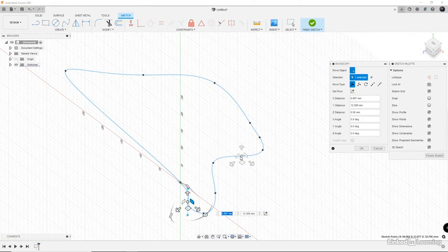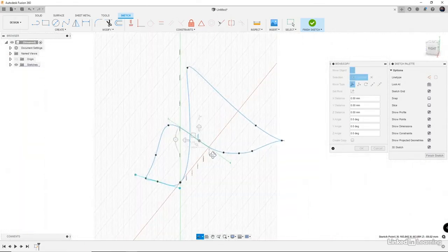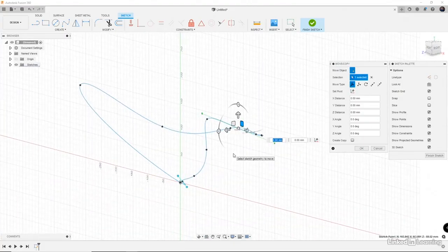The only problem with editing is it's not going to reference the construction plane that it was built on. It's going to reference the original construction that you did. So if you notice, this is referencing the construction plane that I built originally here, and this is allowing me to move this in 3D, but it's not going to re-snap to that temporary construction plane that I built for that point. So something to keep in mind when you're creating reference geometries and parts.